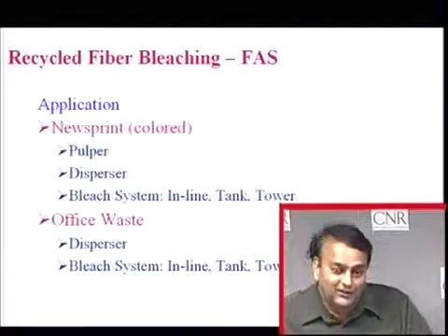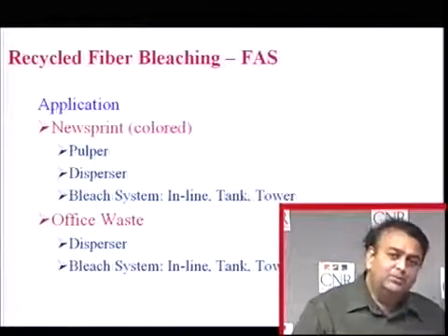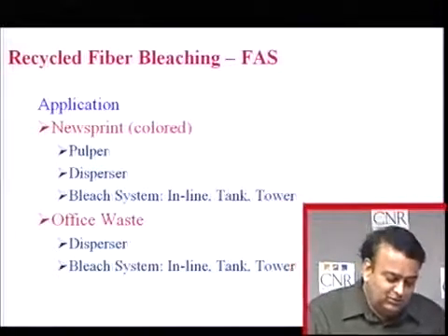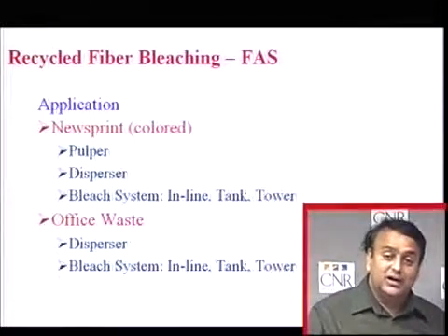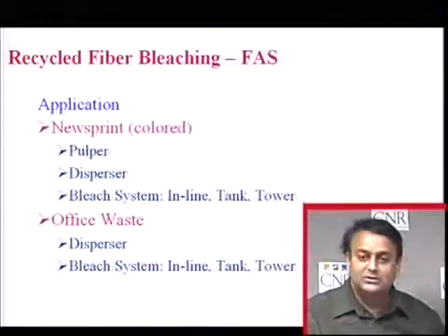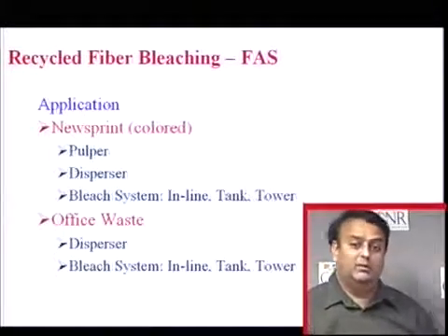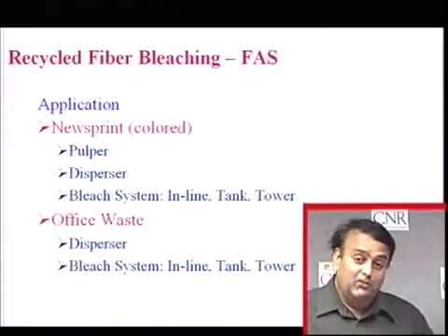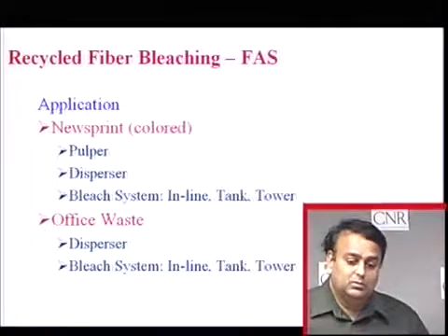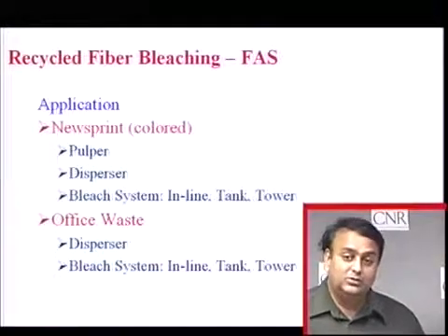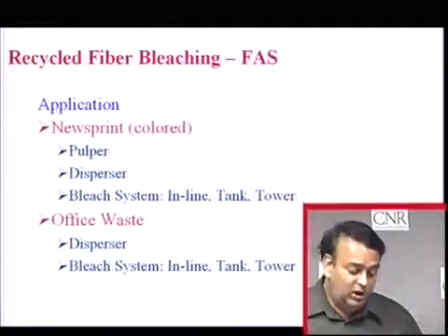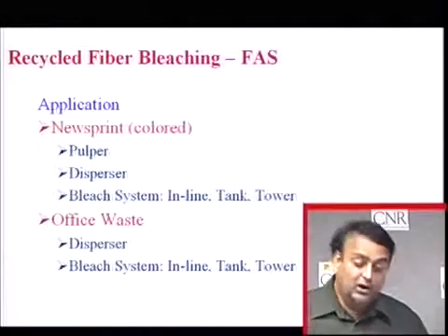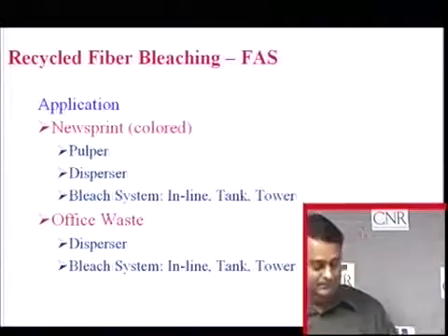Where do you apply FAS? On colored newsprints, there are pink colored newsprints and slightly blue colored newsprints available. There you can use FAS to remove the color in the pulper, disperser, inline, tank and tower bleaching. Where it is more popular is for office waste color stripping. For stripping red, yellow, blue dyes, FAS works very well. So, it is again added at the disperser and also inline, tank and tower bleaching.